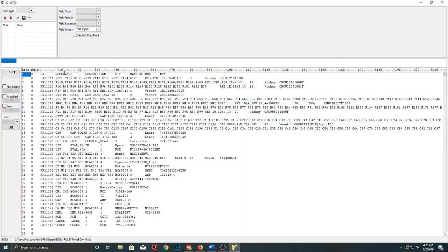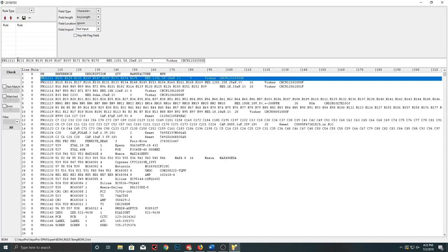Double-click the line with electronic parts data. Move cursor to the edit area and right-click. Choose Auto Separator and confirm the character which separates the content. Utilize field import and identify the column of part number, reference designator, description, quantity, component manufacturer, and manufacturer PN. For reference designator, please make sure you select the right separator and link character.